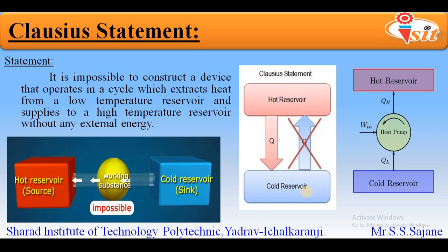If we consider an example for this Clausius statement, then we can simply consider our refrigerator or air conditioning system. If we assume the example of air conditioning system, then whenever the AC is installed in a particular room whose temperature is to be controlled, what AC will actually do is take electrical energy, which is nothing but our work in the system.